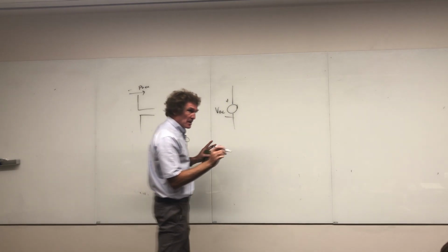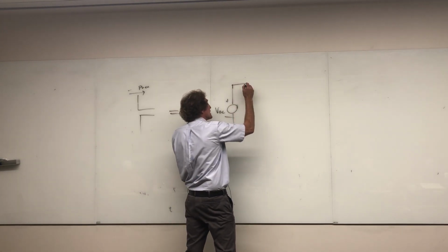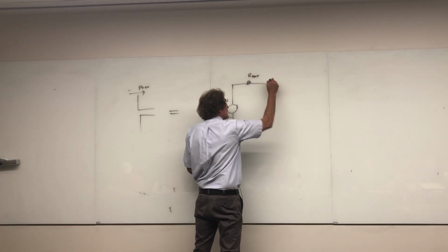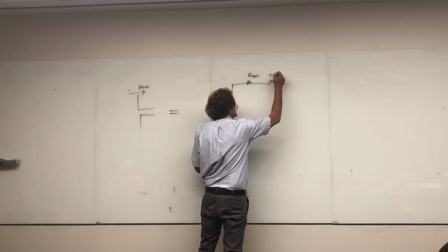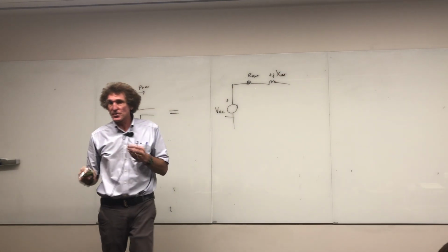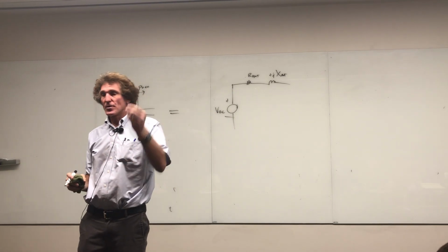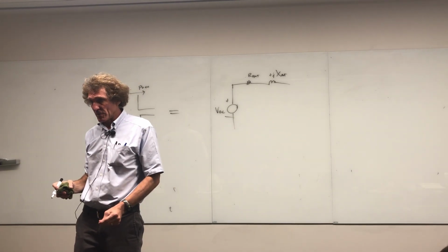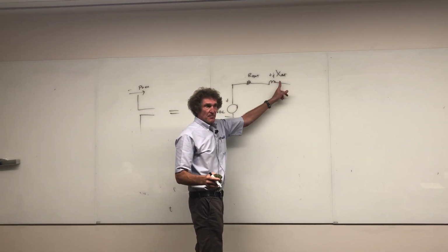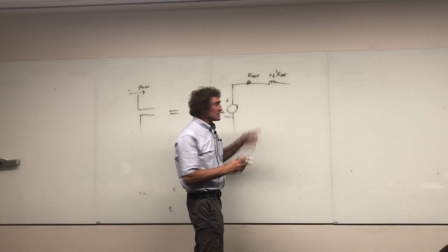And then there is going to be the impedance of the antenna. That's going to be the R of the antenna plus jX of the antenna. That's the imaginary part, like 73.2 ohms plus j42.5 for a half-wave dipole. Follow me on this? And by the way, this doesn't have to be positive. It can be negative as well. That's irrelevant. But that's internal to the antenna.